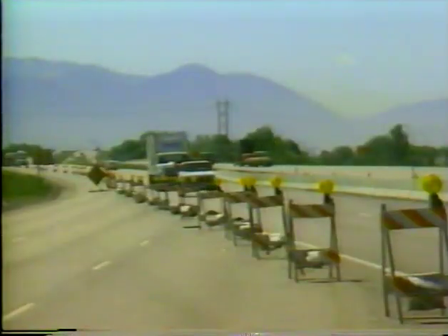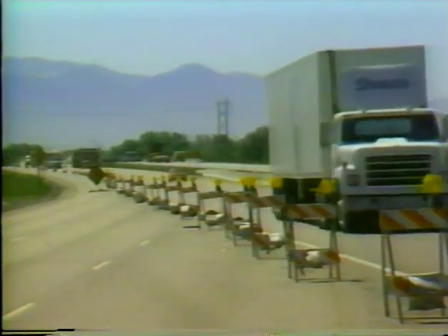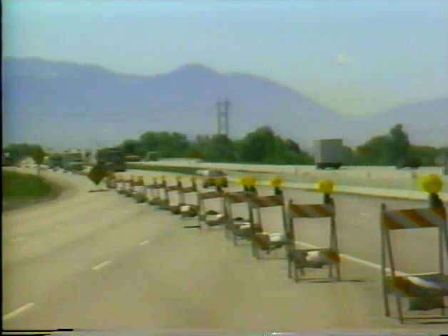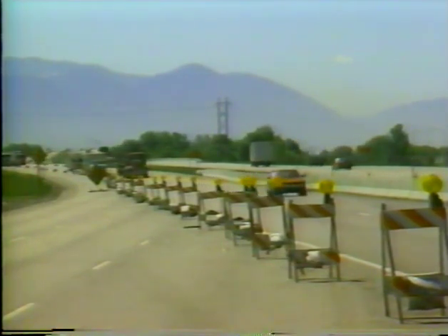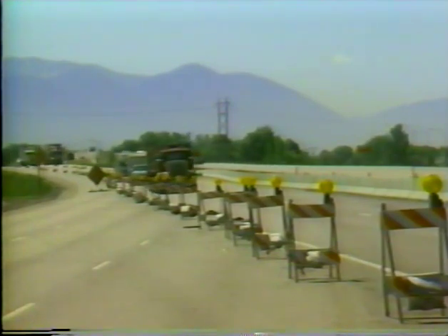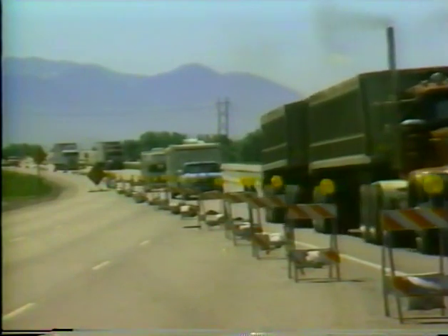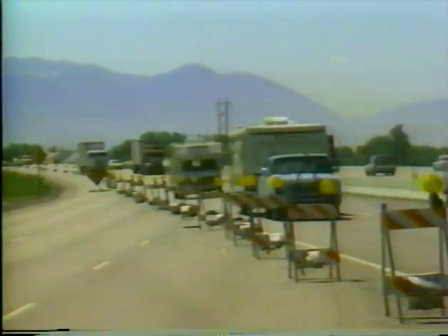We've already talked about position as far as the installation of devices goes, but over the course of a project, signs and channelizing devices are often moved out of their original position and alignment. The contractor must maintain the planned position and spacing to provide drivers with the positive guidance they need.